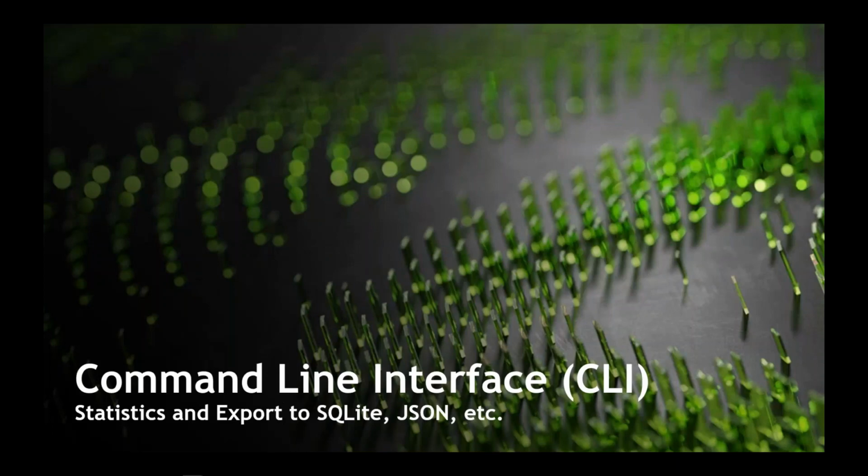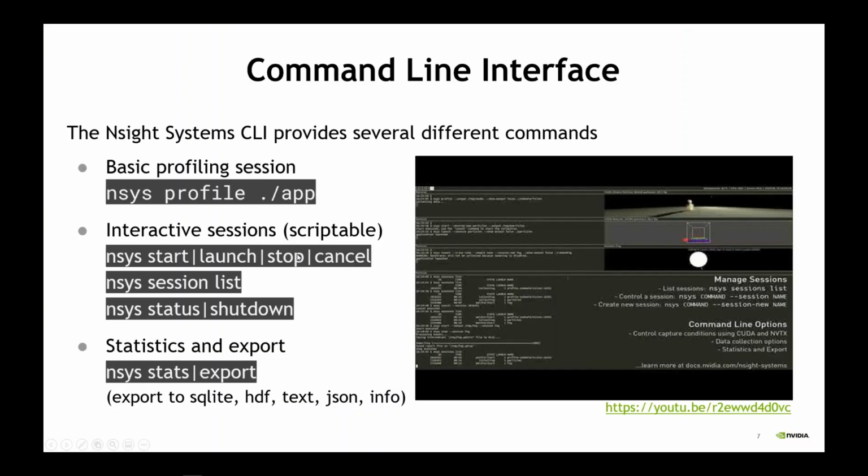All right, so before we start looking at a report and its visualization, we take a look at how the profile is generated. If you are on a command line or in a console, you can in most cases simply use the basic profiling command, which is called nsys profile. If you want to know all about the available options, you can just type nsys profile --help. After the presentation, if you want, you can look at the video linked below, which explains how you can run interactive sessions. But for now, let's ignore it, so you can watch it later if you're interested.